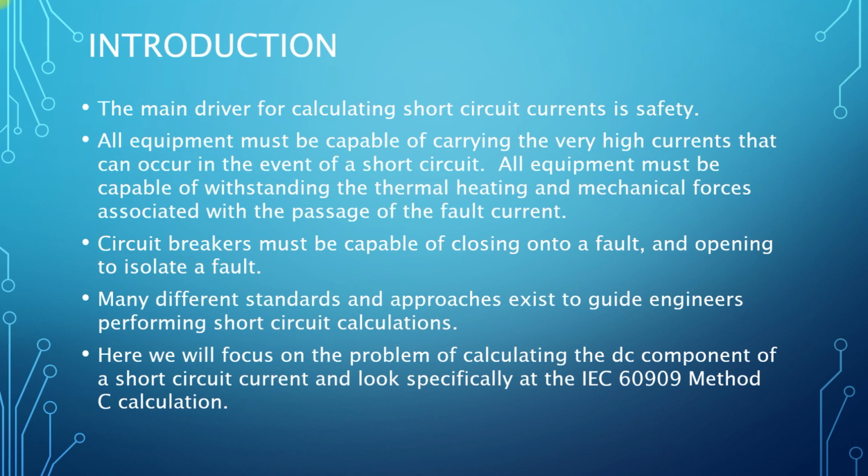All equipment in the power system must be capable of carrying the very high short circuit currents that may occur. The equipment has to be able to withstand the thermal heating effect of the short circuit current and also the mechanical forces associated with the flow of the short circuit current through the equipment.